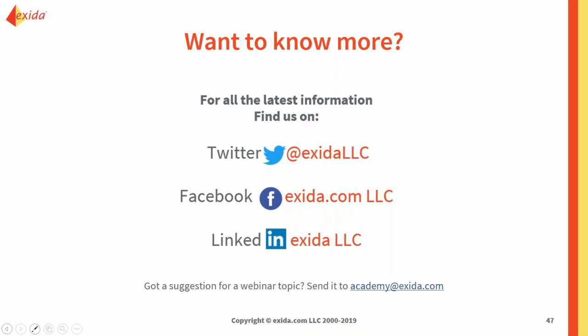We talked about SIL ratings and SIL capabilities for final elements. There was a question wondering if there are logic solvers with SIL capability ratings and architectural constraints out there. Absolutely. Every device, whether it's a sensor, logic solver, final element, they will all have their SIL capabilities. So if a logic solver out there has that quality system that met the SIL capable, then their certificate will say SIL capable, SIL 3 capable on it.